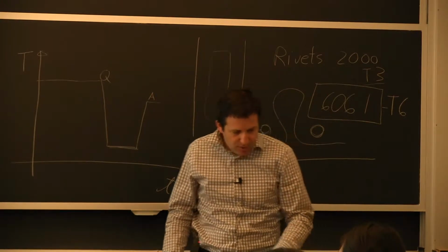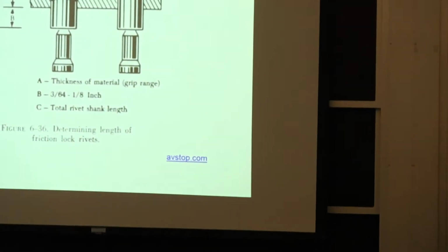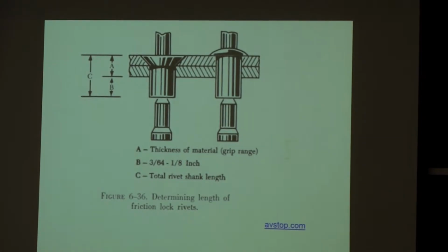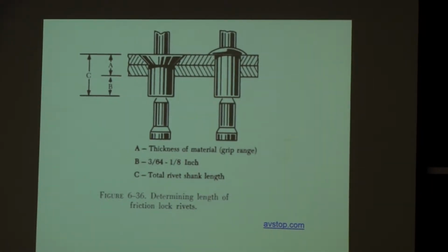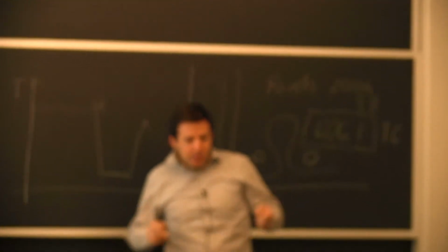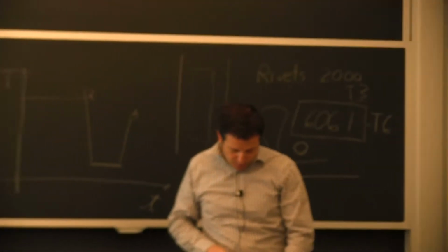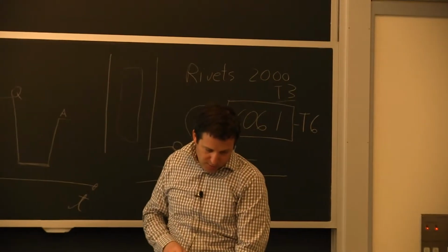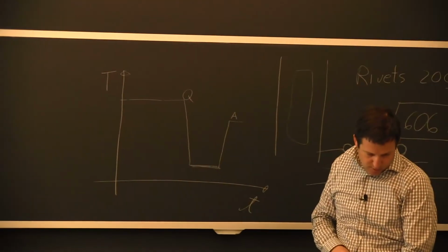We did talk about rivets, and that was tying with what Professor Eager later mentioned here with aluminum alloy, in getting the material really, really soft because of the quenching of essentially a solid solution, something that doesn't have any precipitate. And then as you go through the deformation process of making the head, you start forming these optimized microstructures that give you a good combination of yield strength and strain hardening.